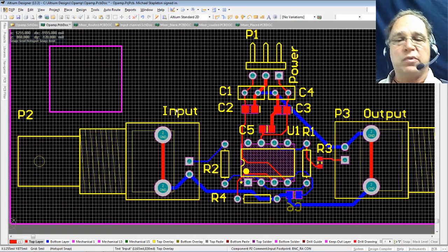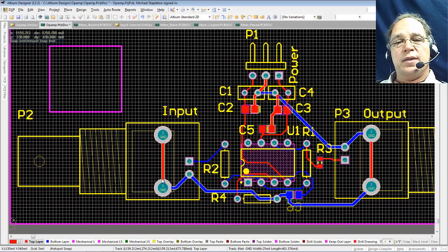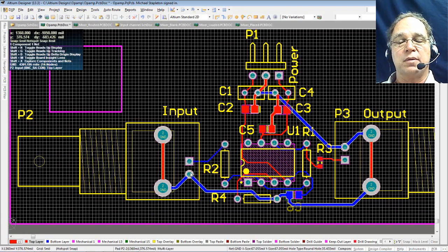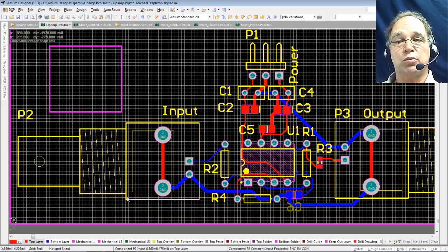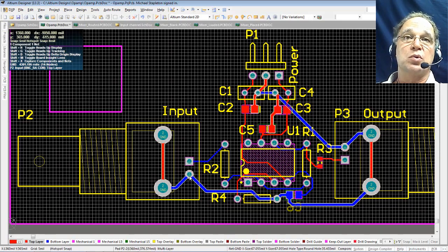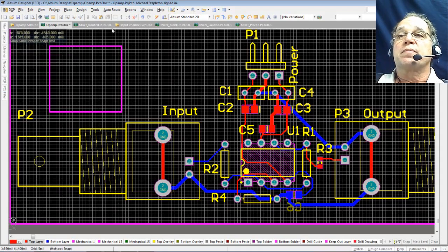Now here's a quick side note before we finish this video. This piece of copper is red right here on this BNC connector, and that is on the top layer. When I put this component on this board to solder it, these connections will be soldered from the bottom because they come out of the bottom of a little black cube of plastic. So I can't see this connection on the top. Here's the problem we run into on boards milled here on campus.